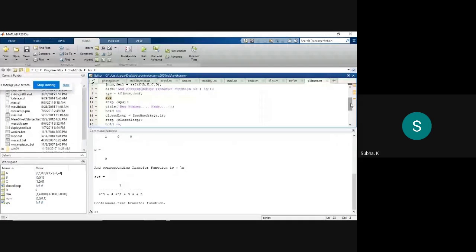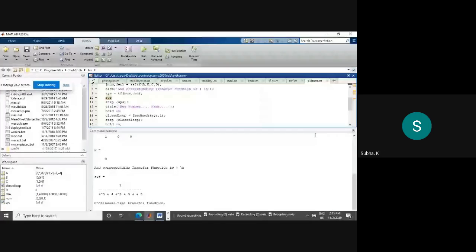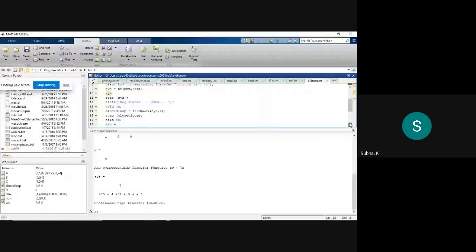That means you did not understand whatever things I was telling you. Using L and T only you can design KP, TI, TD. That only I am asking you to calculate. I am not giving KP, TI, TD; I have kept it. You need to tell me the value. After that only I will substitute and tune it and observe how much the settling time is better.